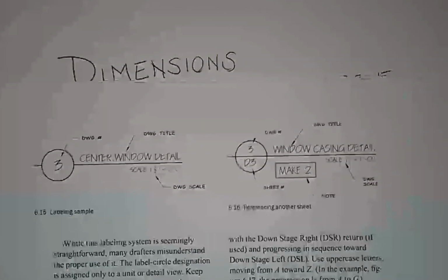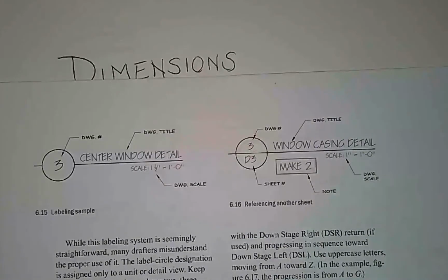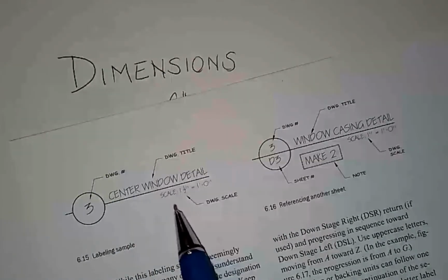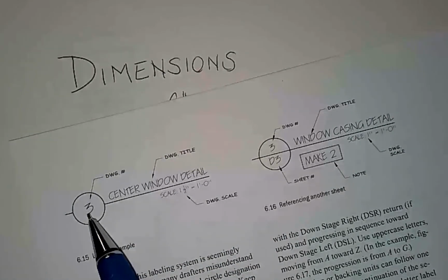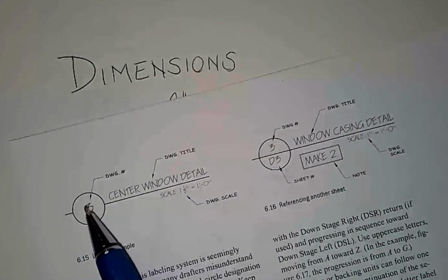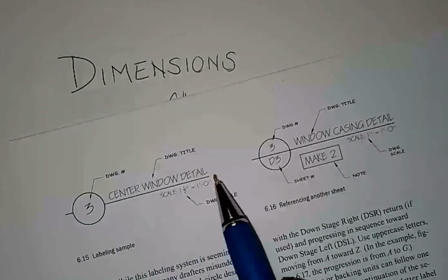This is going to be a little more clear on a full drawing set, which is why I'm going to send you the Lysistrata drafting package, and you can look at the way that I'm connecting things from the ground plan into the elevations. But typically your drawing label is going to give the title of the drawing, the scale, and the drawing number. When we're talking about walls or scenic units, we would use letters as drawing numbers. So it might be A, center window wall, right?